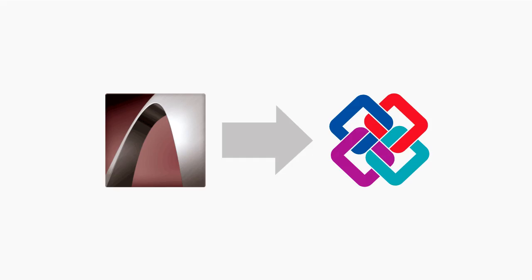ArchiCAD 18 now comes with a data mapping function, which lets you assign all schedulable ArchiCAD parameters and quantities to IFC model elements as IFC data. Why would you want to use data mapping? Here's why. Data which mean the same thing in ArchiCAD and IFC only have to be entered once.